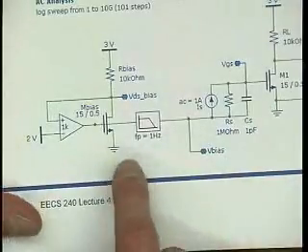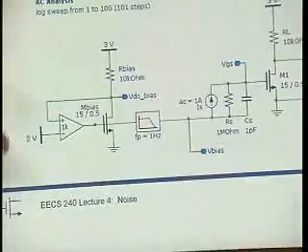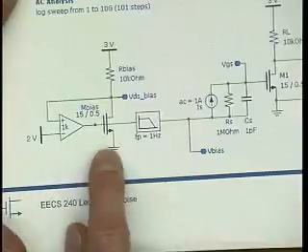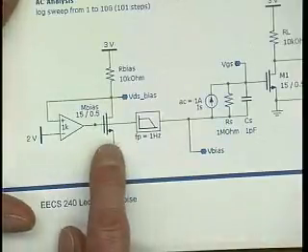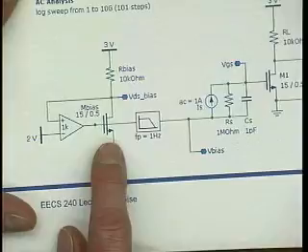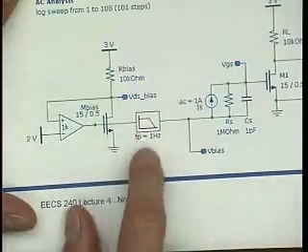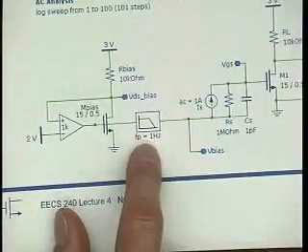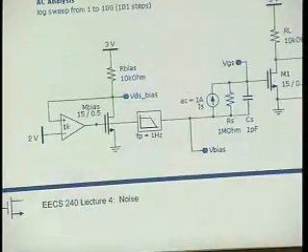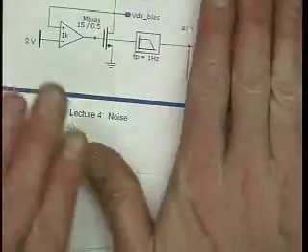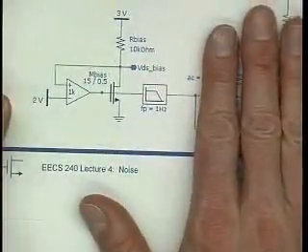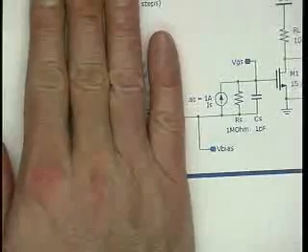This circuit, of course, also produces noise, and I have not found a way to turn this transistor, for example, into a noiseless source. So, to eliminate the contribution from that noise that would taint my simulation, I put a very narrow band low-pass filter here in the middle. This is really just SPICE tricks. You can invent your own. There are lots of ways to do that. This is the circuit that we want to analyze.